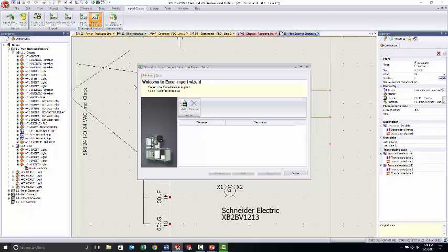If you use a previous project you've done and you're using it for basically putting components on there, first off, you don't need necessarily all of them that were in the previous project. Right. Can you dump the unused when you're done? You could either dump the unused when you're done, because of course anything that was on that design rule check that you didn't use, you could just go ahead and delete from your component tree, and it would be cleaned up. Okay. Yep. So that is another way that you could utilize that, yes.